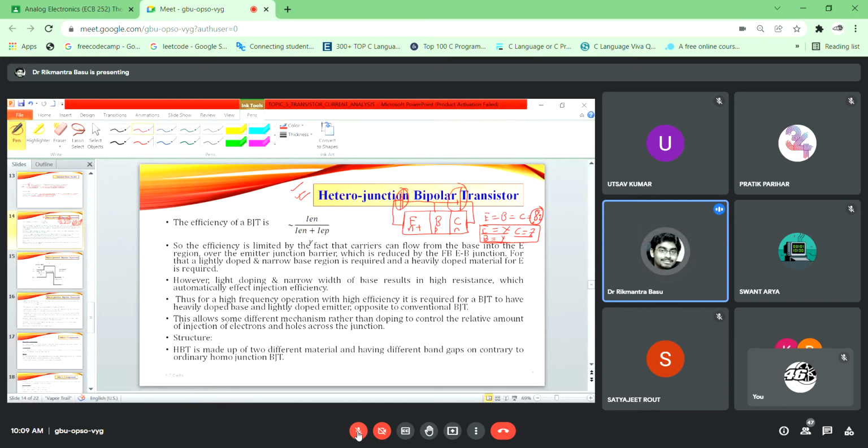The problem is always when the transistor is in the active region, to make a stable active region operation or stable amplification. The most important thing for stable amplification is the emitter. We do make it heavily doped, but the design of our circuit is in our hand, so that the heavily doped emitter can shoot more and more electrons to the collector. Then only more and more electrons will reach the collector, and amplification will be possible through V equals IR, a linear relationship. Just buying an n-plus emitter from the market does not ensure that the emitter will inject more and more electrons to the collector. No one has ensured that; you have to take care of it through your design.